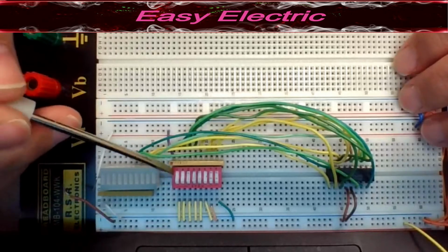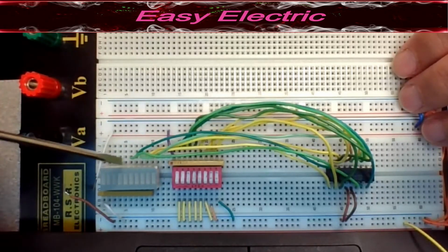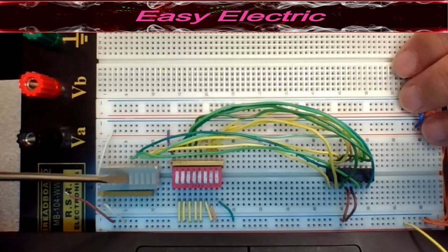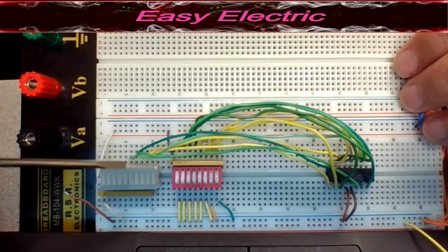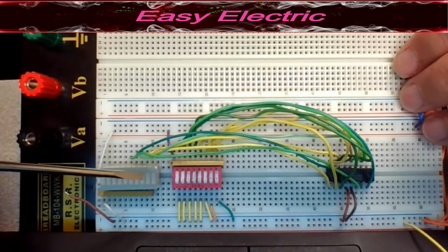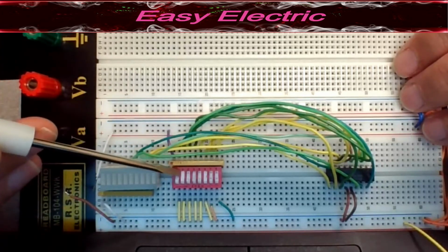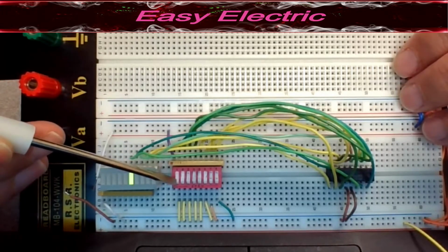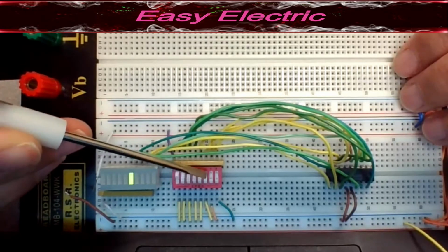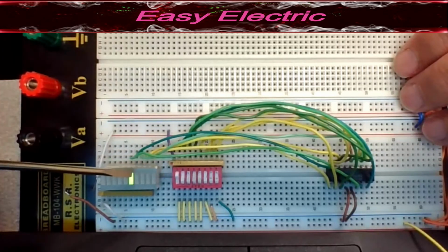Let's test it. As I mentioned, this is the highest value bit. If you check your output port, here you have the carry. So whatever you see on the middle light is C4. Then you have S4, S2, S1, and S0. So the LED on the right side is the highest value, and whatever you have on my left is the lowest value. Right now everything is 0. If I just turn on B4, definitely I will have 8. A is 0, B is 8. So 0 plus 8 is actually 8. That's the reason you see 1, 0, 0, 0, which is 8.